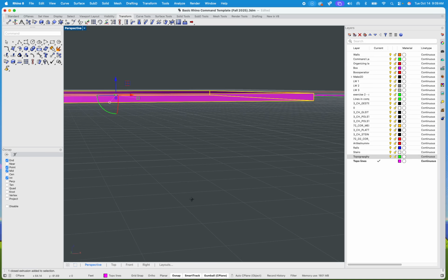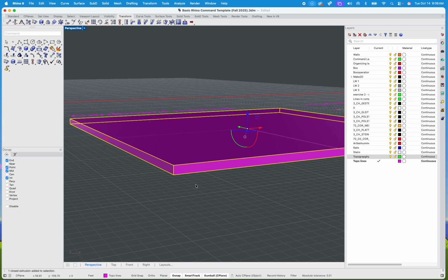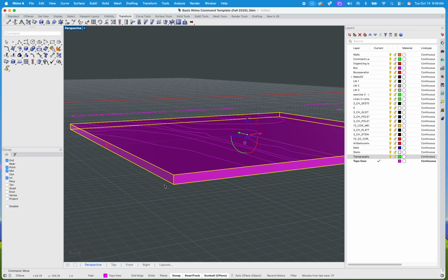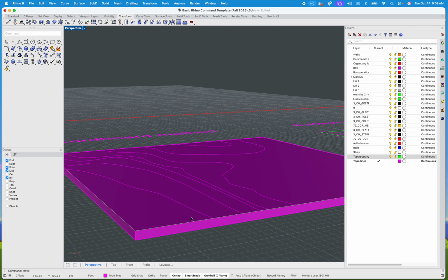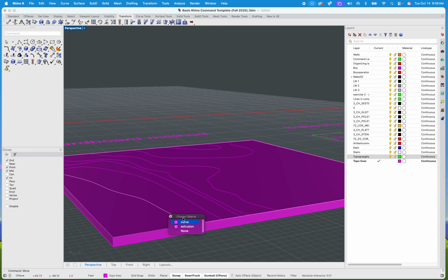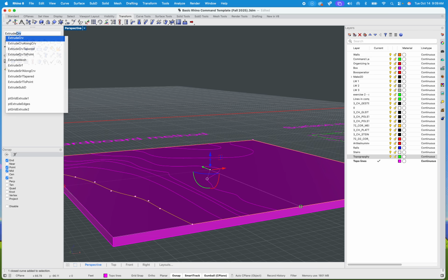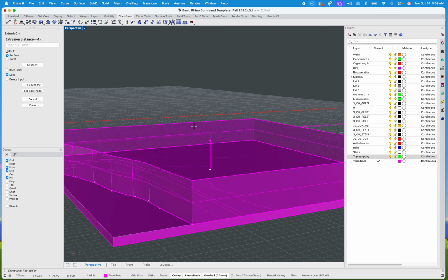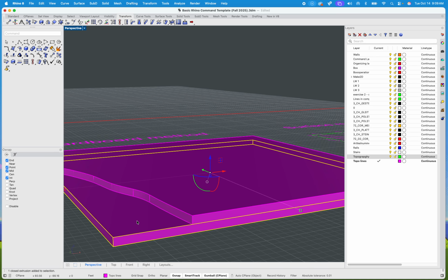Dang it, why didn't it go down? Anyway, maybe it doesn't. Or maybe I'm doing something wrong. But I like to do it in a down method and kind of grow it as I keep going. So I'll take the next line. Again, extrude, 1 foot or 12 inches. Awesome. I'm going to take both of those and move it down.